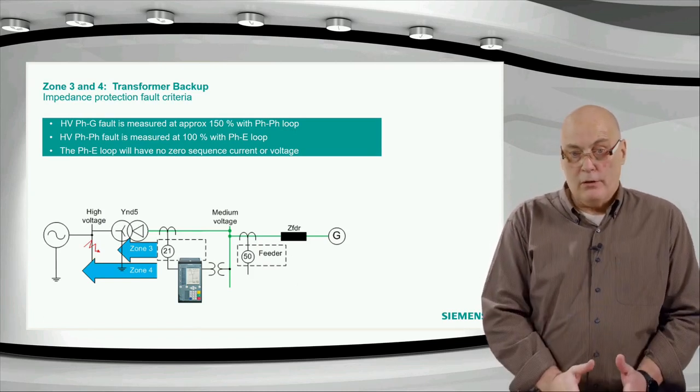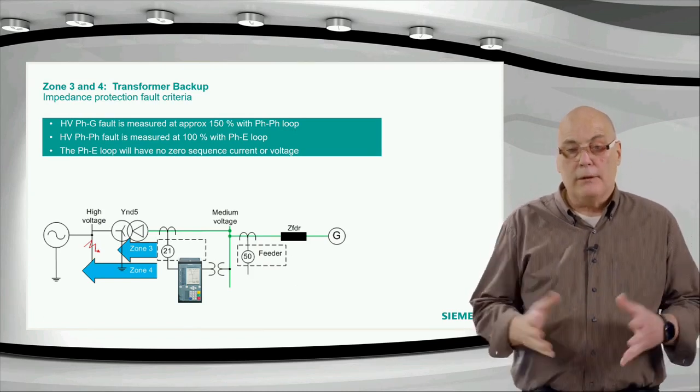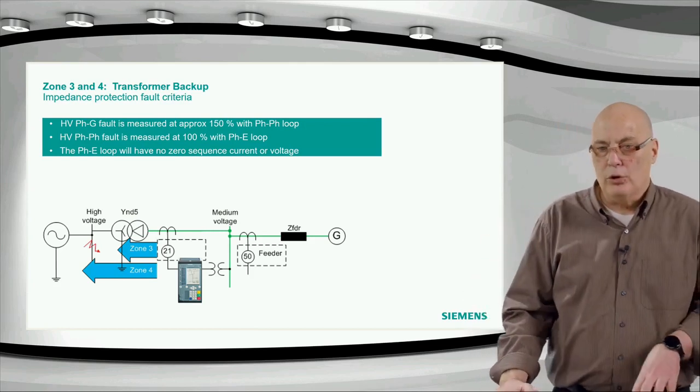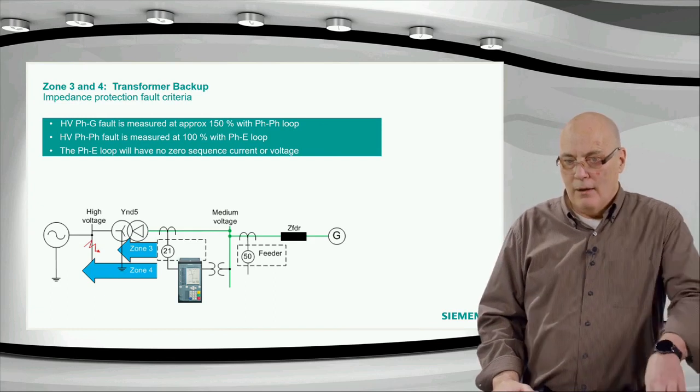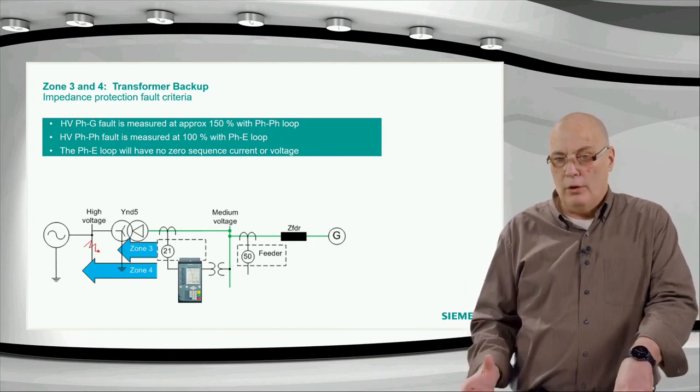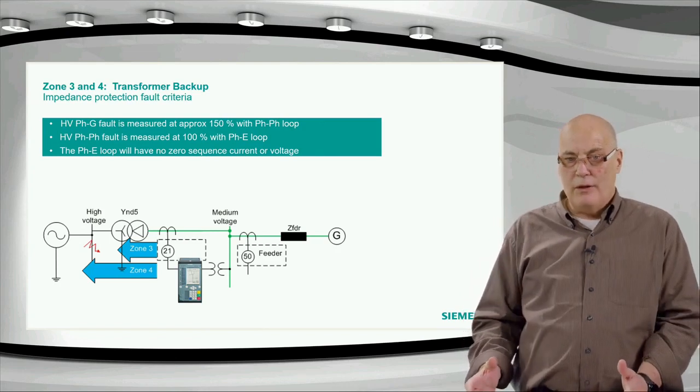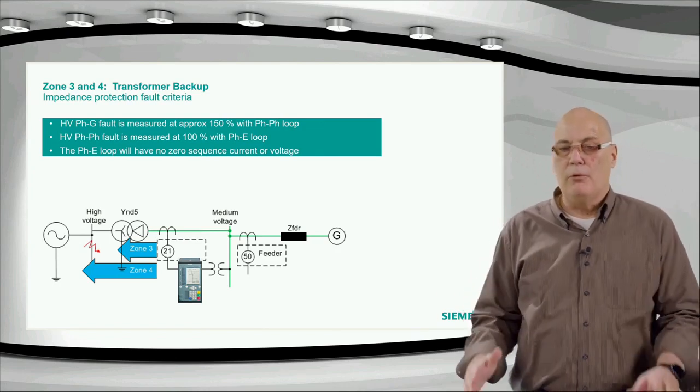Also star-star transformers if they are not both grounded, but those are unusual. A Y transformer with two grounds is unusual. If there's a delta in that, like you would have an auto transformer, the delta would also shunt the zero sequence to a large degree. The zero sequence would not come through that transformer at all.